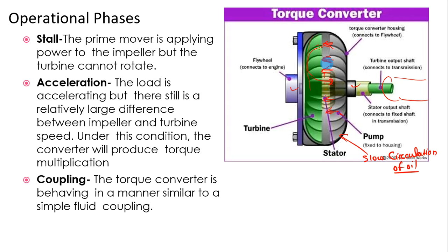So a built up output velocity of 2 to 3 times the output velocity due to the engine alone is achieved when the turbine is stationary. So this makes the turning force of the turbine 3 times that of the engine.